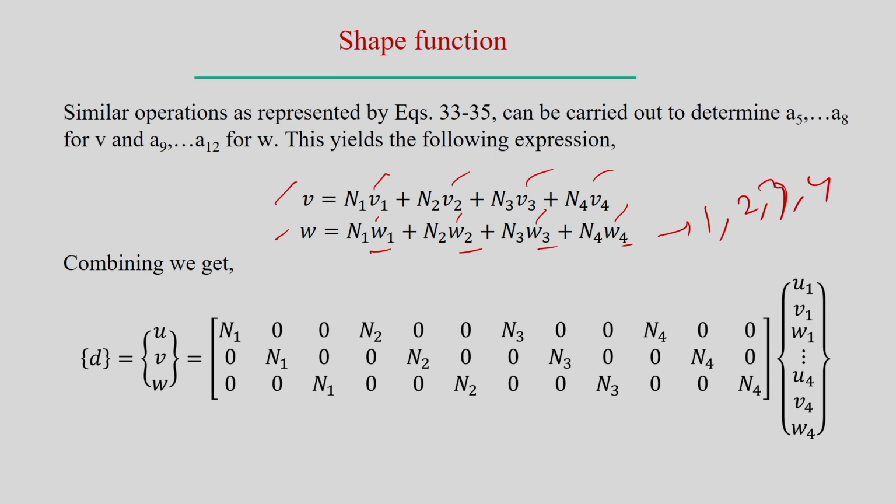So, once we get all these values of the general expression for u, v, w, the displacement field in general, d is the displacement field, d consists of the displacement vector u, v and w, all three components, because the displacement field in general u, v, w corresponds to the x component, y component, z component.